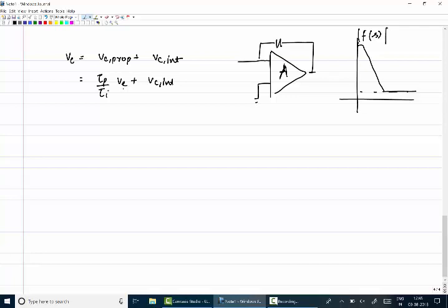Now look at it. If I give any change in the frequency error, my V error can change and my VC integral can also change, right? But if my phase error has saturated, at 0.5 something, then my V integral can't change at all. This is all the loop dynamics, so it cannot change. That is why, if you give a large step, it may turn out that the phase error is also saturated, and that's why my V control for the VCO is not varying and I am not able to lock in.